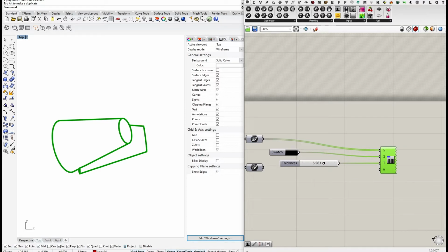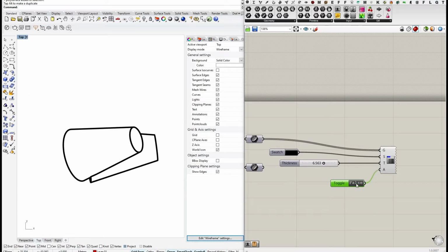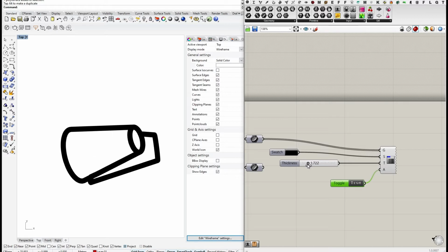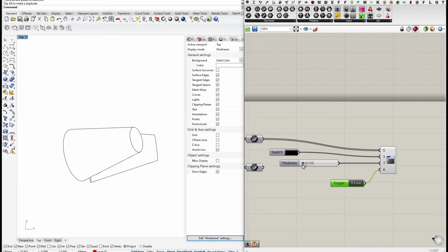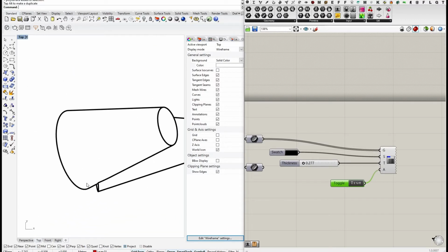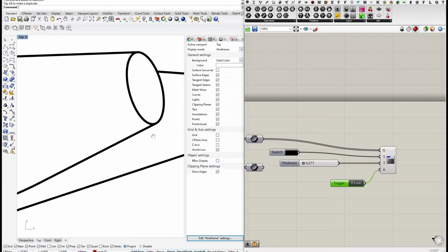It asks for a Boolean value, so either opting in for keeping it general, so fixed to your screen pixelation, or going in true, which generates a true thickness of the line, which our value is currently very high, so we would reduce that to something slightly thinner. And here now you can see that when we zoom in, the line thickness actually becomes bigger.